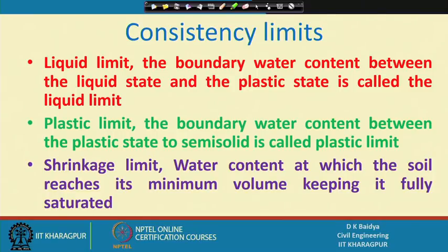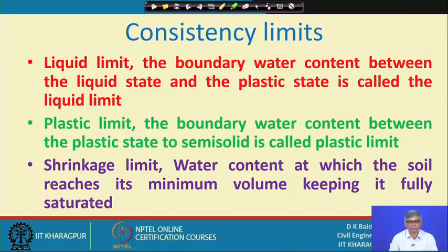As I have told, this is one sort of classification that can be done if the particles are bigger and have no plasticity. But if the soil contains mostly silt and clay, sieving is difficult, and we have to do some other type of classification.